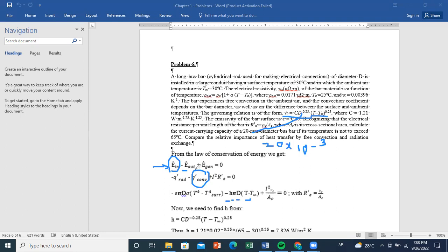we have here to determine if we have energy in or not. Here, if you want, you have just generation of energy and you don't have fluxes that are coming in to the system. You are just having fluxes getting out. So E dot in is 0 in this problem, okay? How it can be different than 0 if you have absorption, for example, of heat from the outside environment.